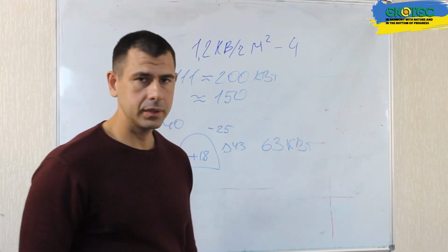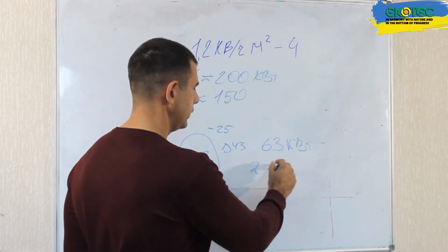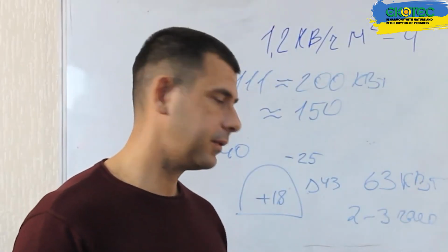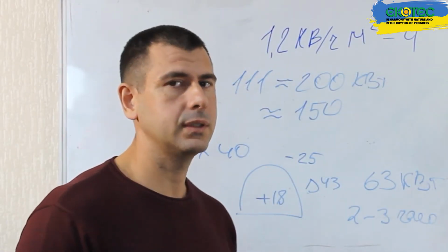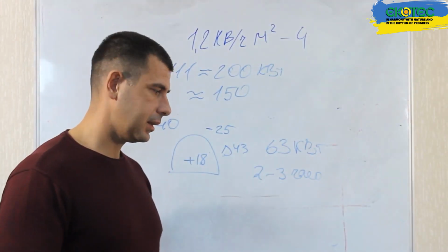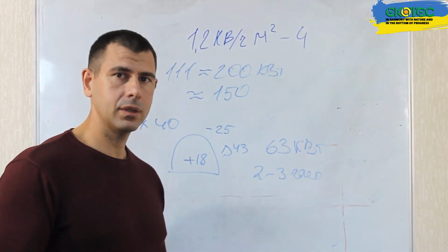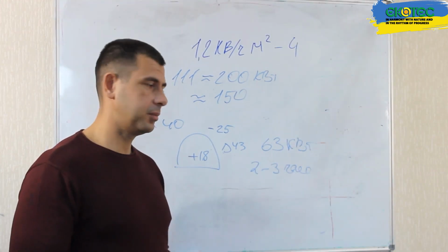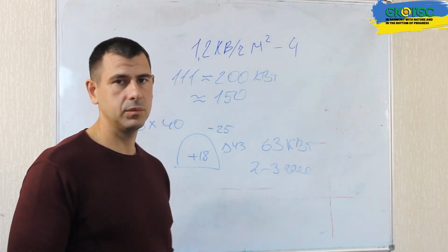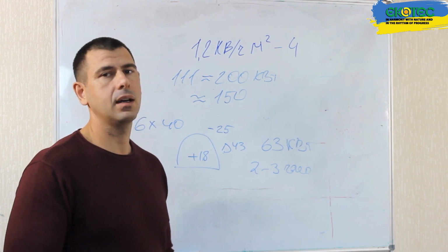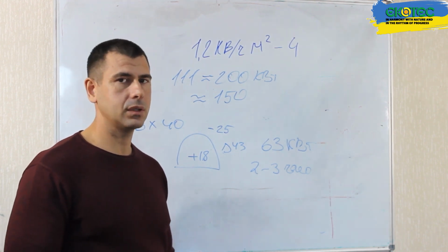In this way, we can save about 20 tons of conventional fuel over the entire period. Conventional fuel in our case refers to firewood, where 1 cubic meter of firewood releases 2100 kilowatts of heat energy. So, we can save 20 cubic meters of oak firewood. Whether this is a lot or a little is up to you. For a 240 square meter greenhouse, we save 20 cubic meters of firewood.